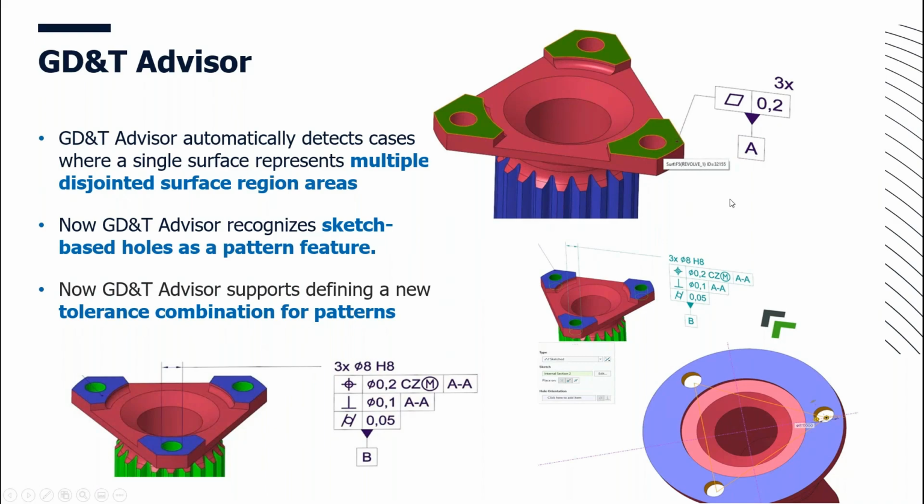In the past, Creo saw that as one surface, which it's not, but it's built like that, and then the cutout is made later on. The same goes for patterns: it understands that it's not one, but multiple ones, and combines that dimension. So what is powerful is, if I'm selecting this dimension, you will see that it highlights the holes.